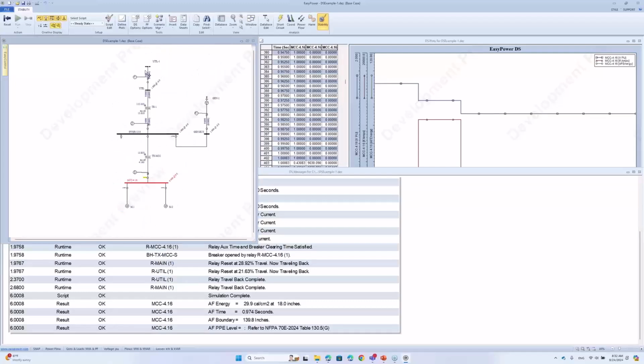The reason is that in a power system, it is really rare that you have only one source which does not have any dynamic stability model, and which does not cause any arcing current change during the arc flash time. It's always changing. Say you have a generator: the speed of the excitation system will determine how fast the fault current can ramp up and how fast it can decay.